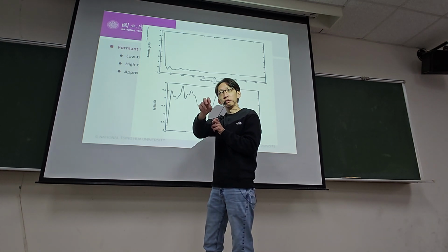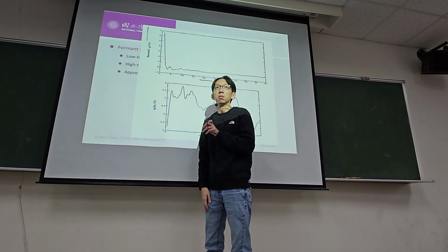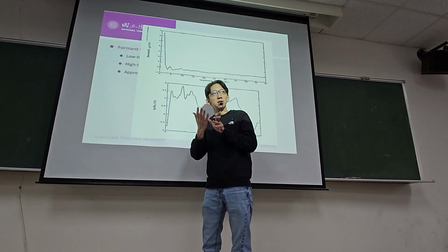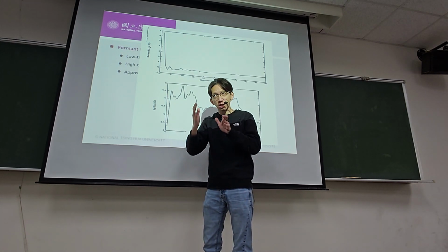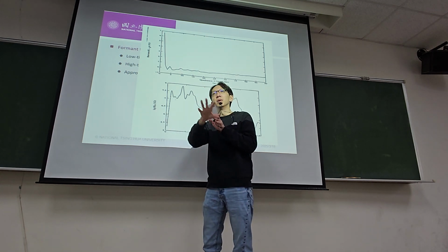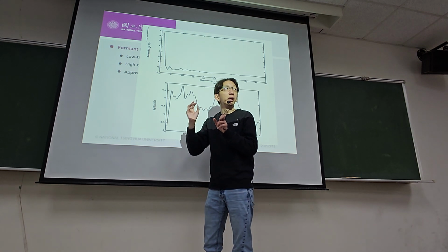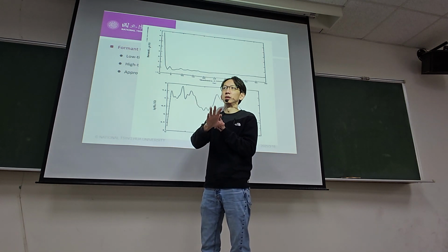That rectangular function, we know, has a high side lobe problem. The same thing applies here, as I told you: the cepstral domain is just like time, but with a log in between. So when you take a segment out of your cepstral coefficients, you are applying a rectangular function onto it.